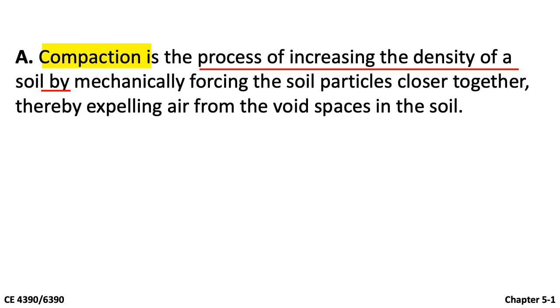Section 1. Compaction of soil and rock. First, what is compaction? Compaction is the process of increasing the density of a soil by mechanically forcing the soil particles closer together, thereby expelling air from the void spaces in the soil. Compaction is like squeezing out the air.